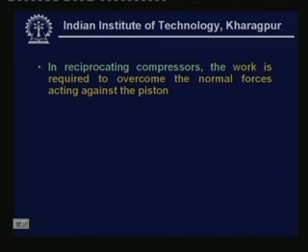And in reciprocating compressors, the work is required to overcome the normal forces acting against the piston. So, why do we require work input in reciprocating compressors? If you think about the working principle of a reciprocating compressor, when the piston is compressing the refrigerant, it encounters a resistance by way of a normal force, and this normal force is due to the pressure acting against the piston.